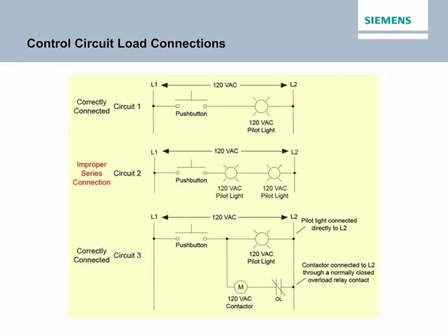While it is proper to place contacts in series, it is not proper to place control loads in series as shown in Circuit 2.